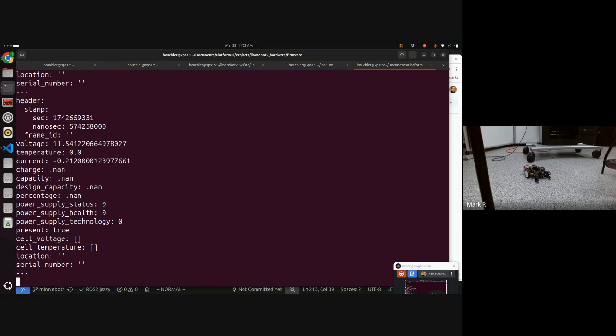Yeah, it's pretty powerful. So you still had to point the robot to your syslog server. Yes, and I'll go through that when I go through robot configuration. But yes, you do tell it where the syslog server lives. Otherwise, it wouldn't know where to send it. So when you're developing, like putting in your custom hardware servo drivers, you can put printfs down in the firmware, and they'll come up through the syslog mechanism and turn up in your syslog on your Linux box. Pretty powerful.